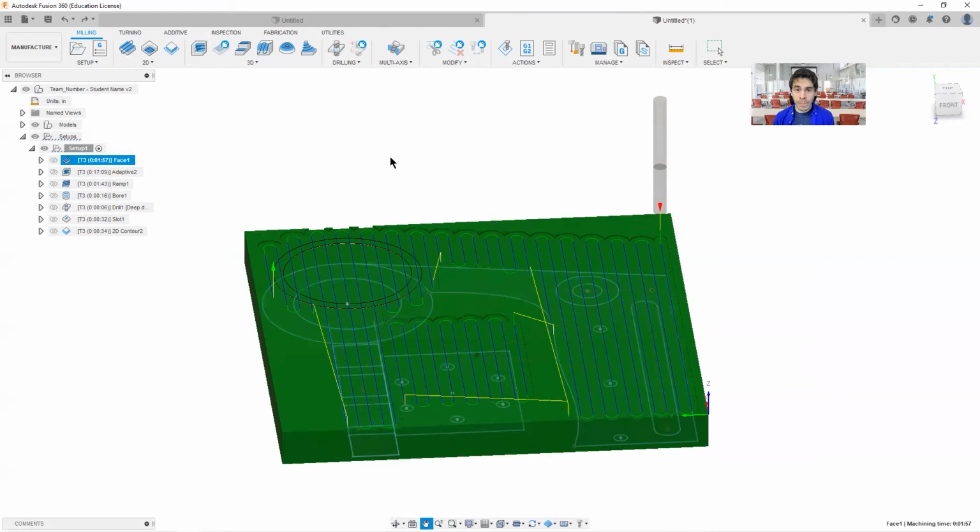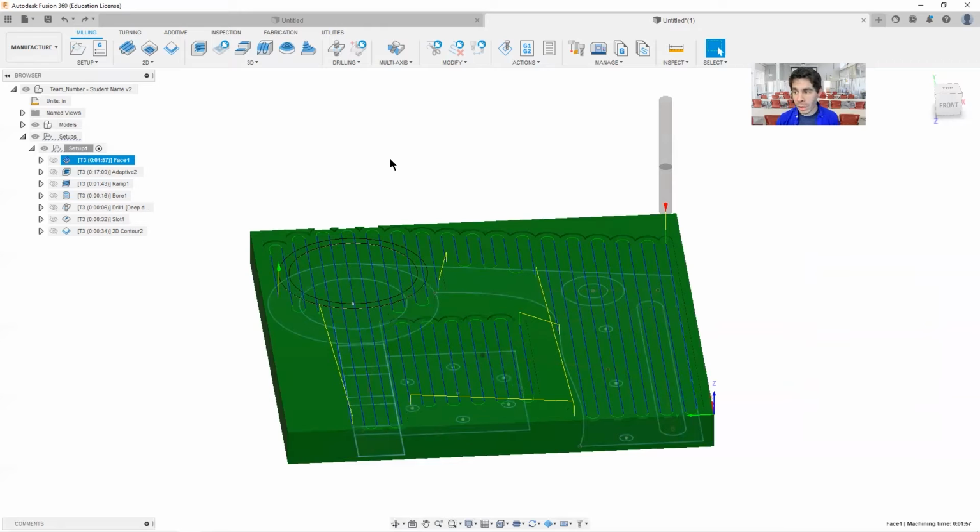But in general, when you're machining, you're going to work from removing the most material as quickly as possible to finer detail cutting with, say, a ball nose end mill or smaller end mills. Now, for our purposes, we're going to try and use all the same end mill. And the rationale here is that we're cutting a lot of parts. We're trying to do it in a very short window. And so not having tool changes makes it possible for us to process all of these files.